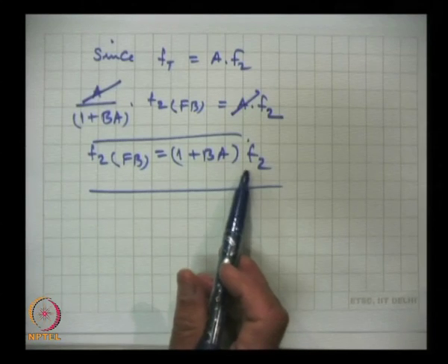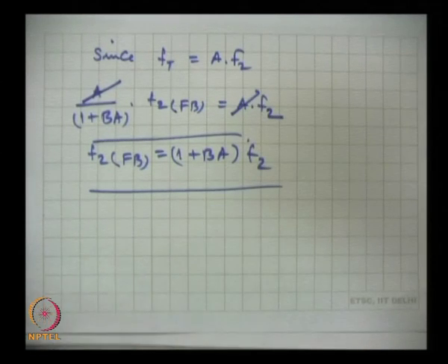So, always remember that negative feedback is going to enhance the bandwidth, but the price which we will pay for this advantage is that the gain falls.